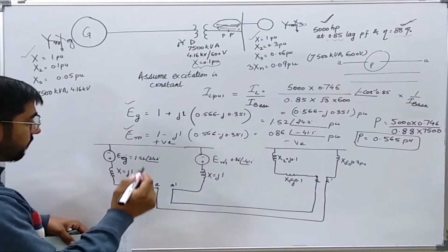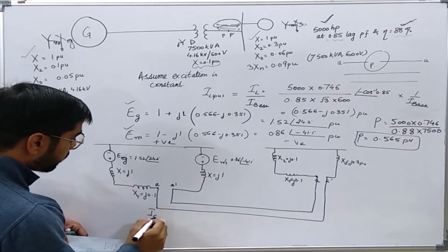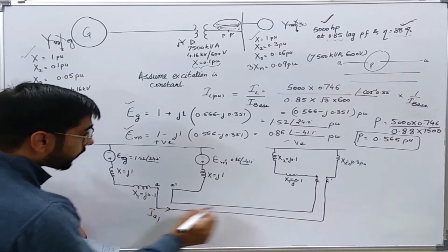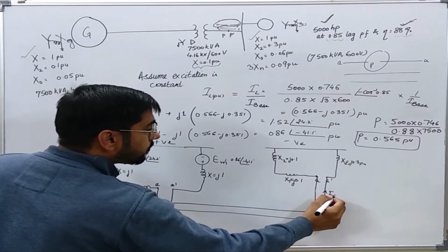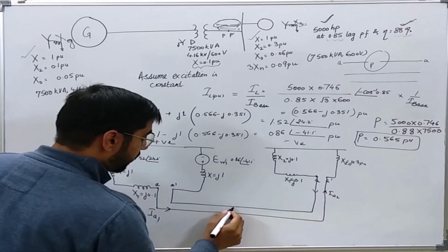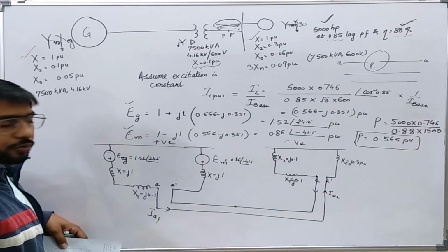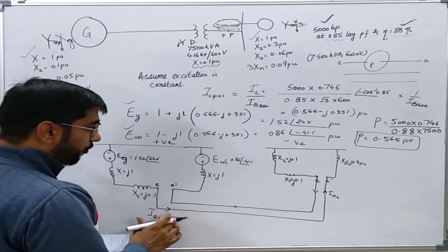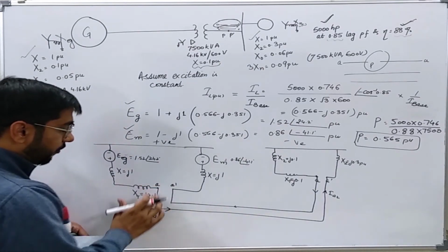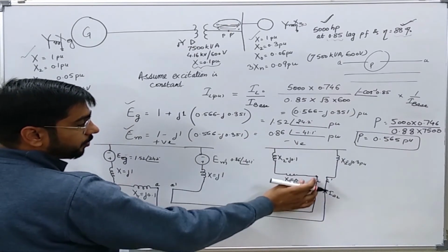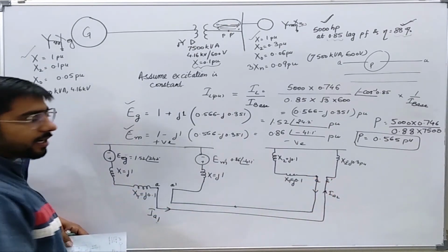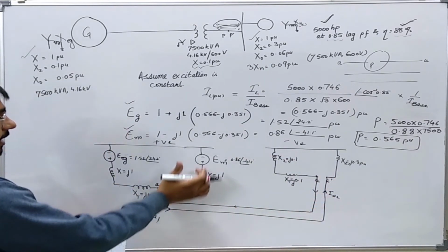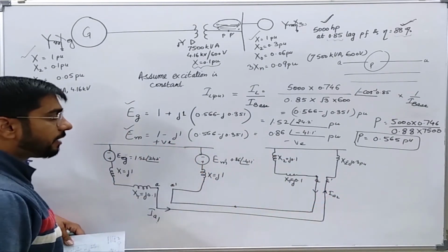Now you see, this connection has reduced to this thing, okay, that current will come out from A dash, A of the positive sequence, either it will enter to this point or this point, it doesn't matter, and it is going to circulate in this and come out from the other point and enter into the A dash of the positive sequence network.